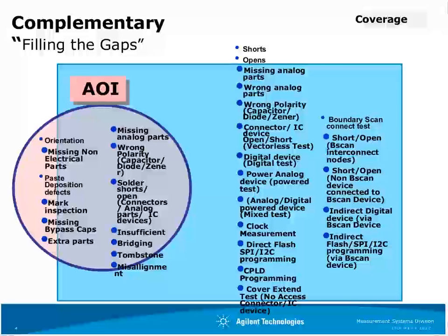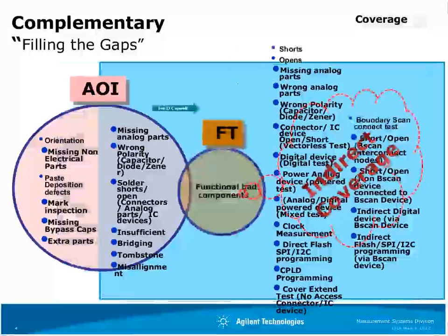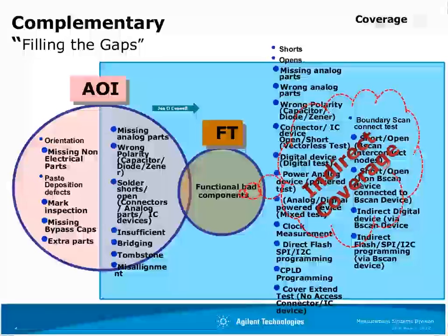So let's examine the contribution from AOI. We have seen very often that introducing techniques like optical inspection is excellent at collecting those gross defects and really is a benefit to your first pass yields. However, if you employ a strategy that takes from AOI directly into functional test, then you're leaving the functional test to provide the coverage for all these other components like shorts, opens, missing and wrong parts. We cannot rely on AOI alone to fill the gap into functional tests.